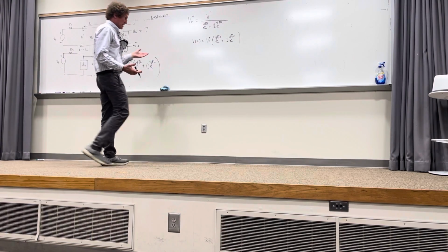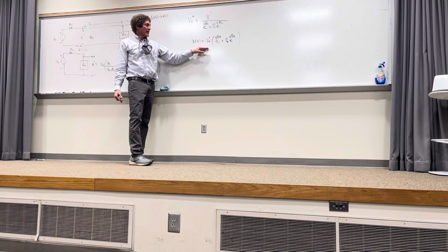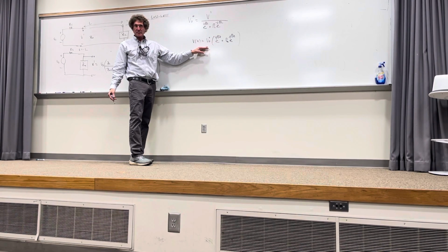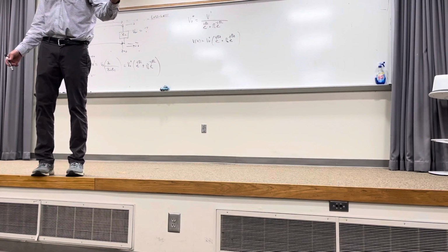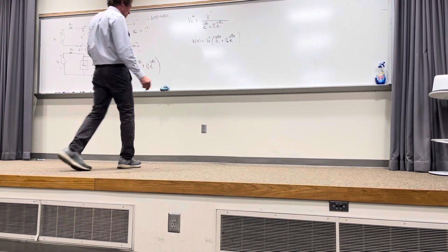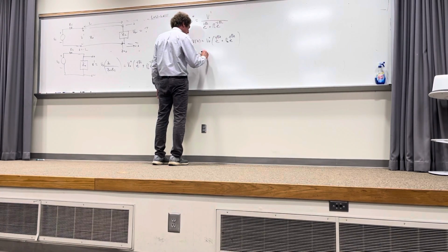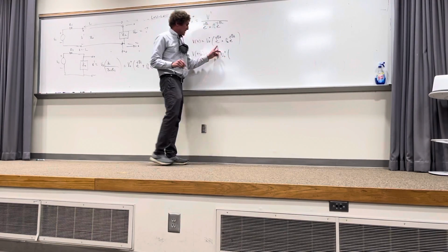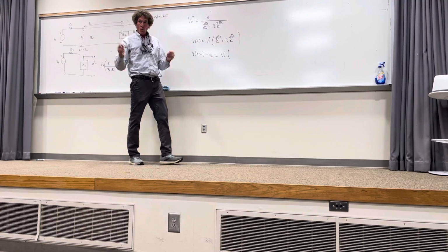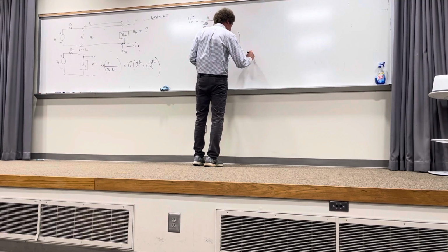Can y'all read this okay in the far back, guys? Okay. If I have that, how do I get the voltage at the load? What is the one thing I do to this equation? If I want the voltage at the load, where is the load? Z equals 0. Y'all follow me? So the voltage at the load at Z equals 0 is V of the load, and that's simply V0 plus times E to the J0, which is 1, plus gamma L. And that's the voltage at the load.